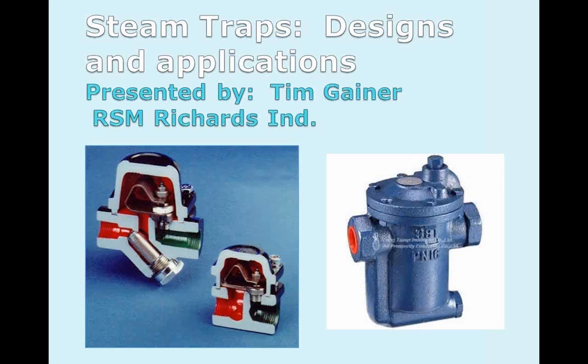And in the main, the loads are actually pretty small. That's one of the things I've run into out in the field a lot. People assume that because it's a large line there's a lot of condensate being generated, but in a lot of cases that's not true. You don't need a huge trap with a lot of capacity on those applications, because the mains are usually insulated, or hopefully insulated, and all you're doing is going out and hitting distribution points, not equipment where you're heating anything.